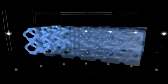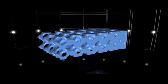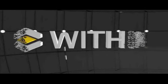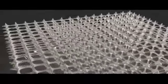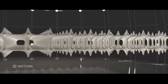Now that was just a cube. We can move on to more complex designs here. And what we do is we can take any component and we can change its material and mechanical properties by filling the solid volume of objects with these lattices. So instead of having a solid block, you can instead fill it with a very complicated lattice, just like bones are filled with the bone cells that are porous or more dense. You can have the same thing with any day-to-day component. What this means is I use less material, it's more environmentally friendly, it's cheaper to build, and you can have a variation in mechanical properties.